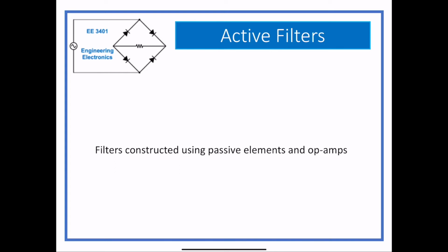The biggest piece of advice I can give you in lab is when you are connecting your op-amp circuit, connect plus and minus 15 to pins 7 and 4 and leave them and don't touch them again for the rest of the day. That's part of your op-amp that doesn't move, doesn't change, and doesn't figure into any equations whatsoever. So you never use plus or minus 15 as an input or an output or a consideration. It just is what runs the device. So do that first and then don't change it. So when you change your circuit, don't move that, leave it.